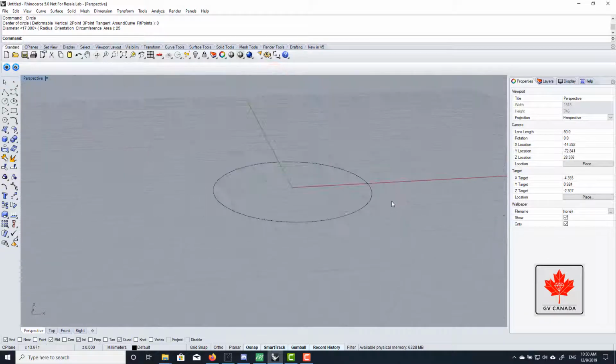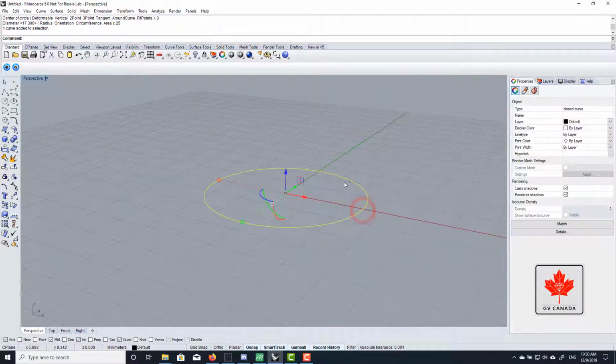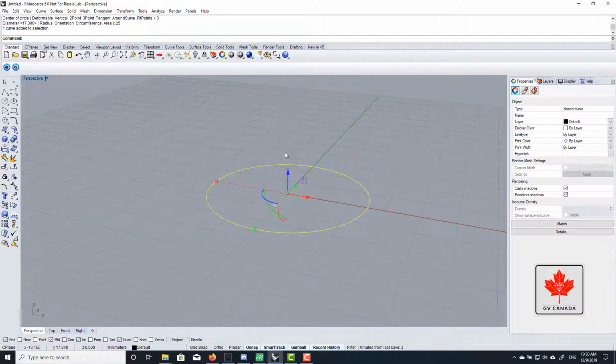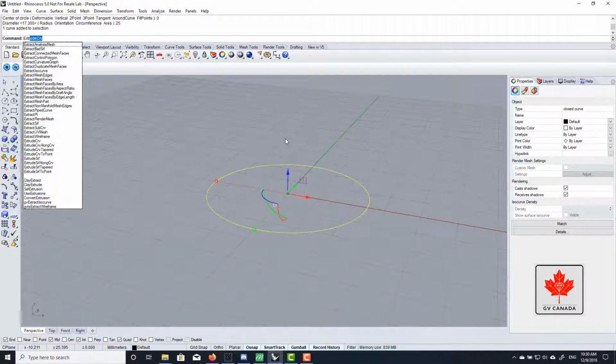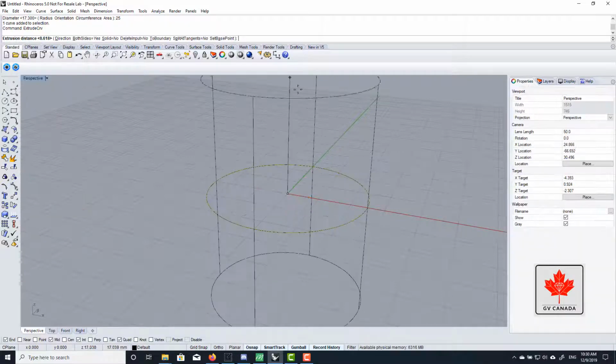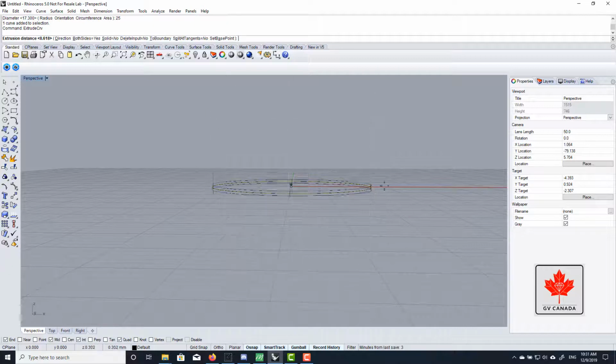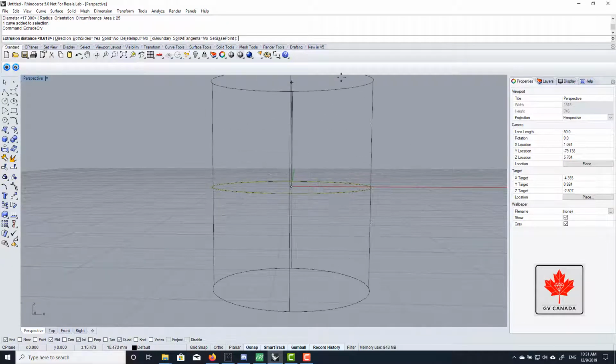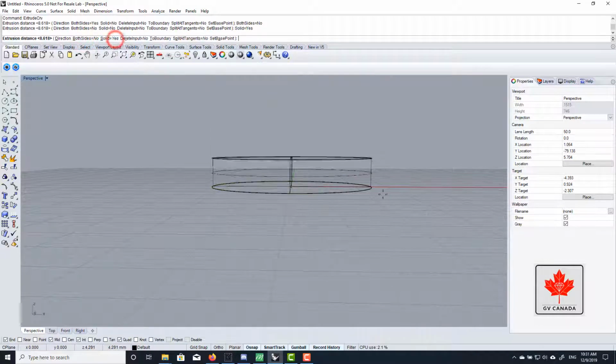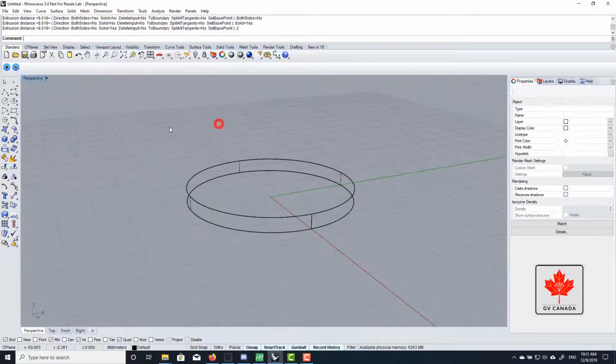And to create a simple flat pendant, I can just grab that circle now and do extrude. So I can type extrude in the command line. Extrude curve, enter, and here you'll see I have the ability to do an extrusion, and this will give the object thickness. The extrusion distance is up and down. So I can go to the command line and do both sides: no. Solid: yes, because we want a solid object when it's extruding. So I want to type in the extrusion distance to be, let's say, 2 millimeters. 2, enter, and we have an extruded object, 2 millimeters.